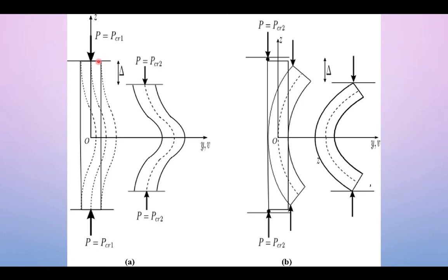Now why did it move? Because till now we learned that axial forces directly transfer the force without any instability. Every structure in the universe has stages of equilibrium, and the structure will give the minimum possible load. Consider the system in the figure. I'm showing in the figure that the deflection in the system is very small. The column is slightly buckled. Now if you take the equilibrium of the buckled shape of the column, you find the load required to buckle the column is less than the load actually carried by the full cross section.